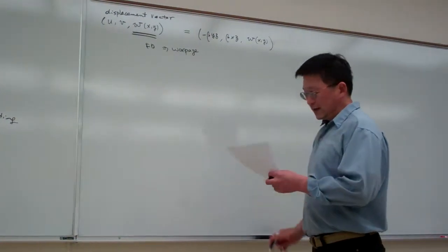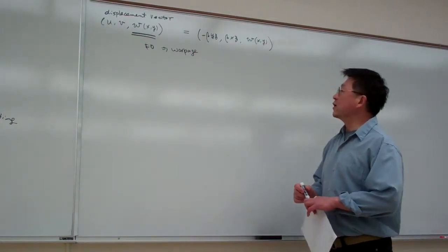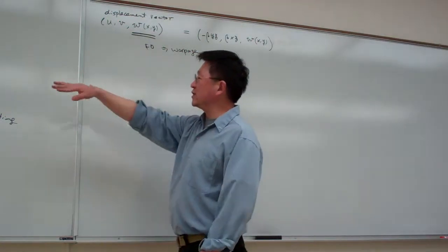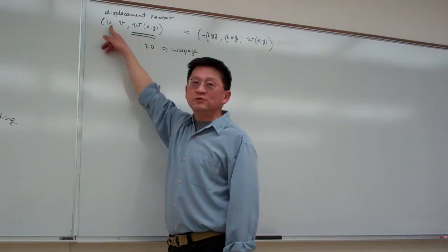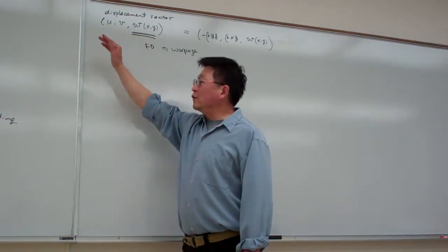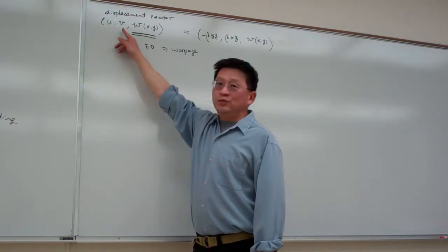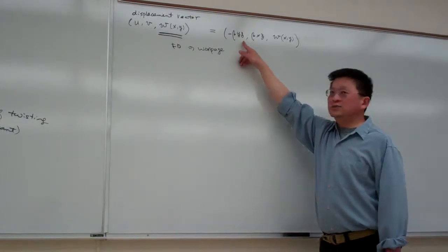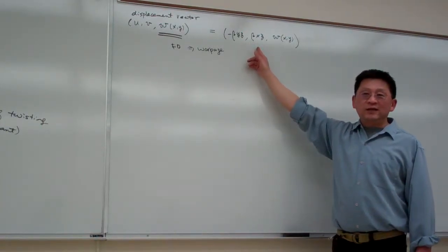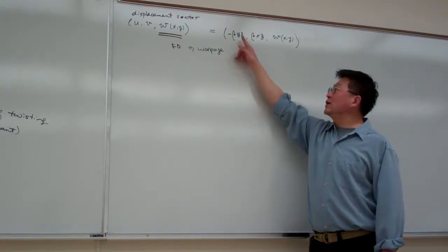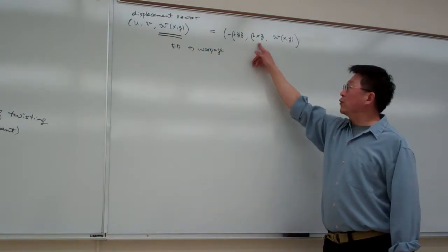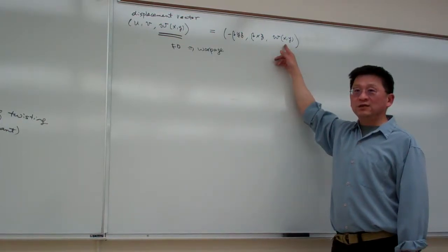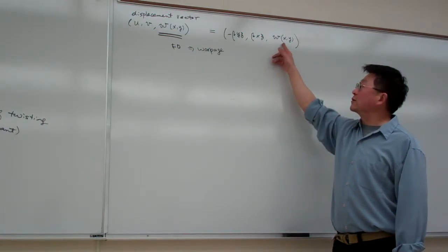So keep everything, and we move on. Once we have a displacement, you can see this displacement is better than nothing. Before we proceed, we just assumed the displacement is u, v, w, where u is a function of x, y, or z. Without any assumption from the very beginning, those are implicit functions. But after imposing assumption 1 and assumption 2, we can have the explicit expression for the two components. So that's what I said, better than nothing. At least for these components we know the exact expression form, leaving w still implicit. That is the effort we're going to spend through the whole chapter, dealing with this term.